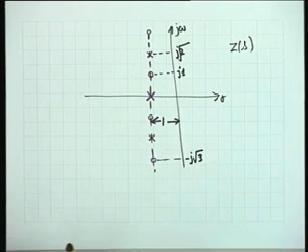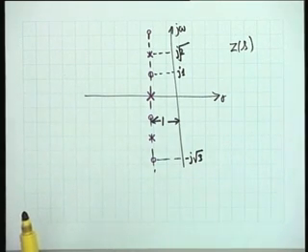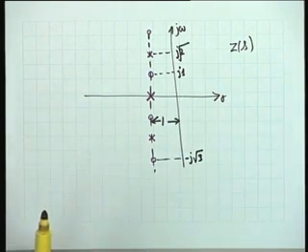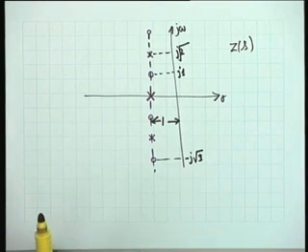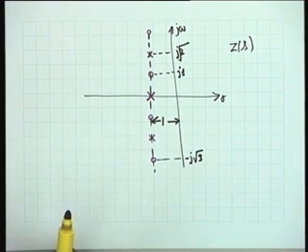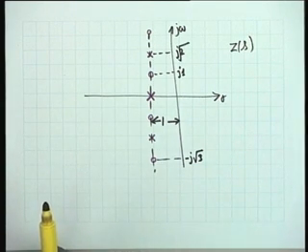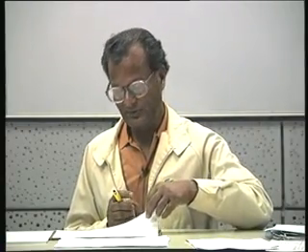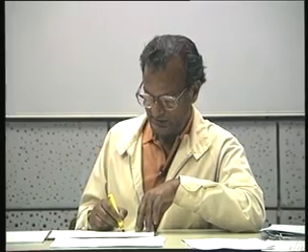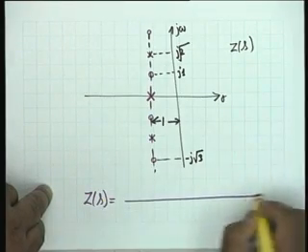1 is the simplest number, it is a very nice number. So the first thing is that we can synthesize it within a constant multiplier. Second, the poles and zeros are neither on the j omega axis nor on the real axis. There are complex poles and zeros, okay. So let us see what we can do about it. Let us write the impedance function within a constant multiplier.